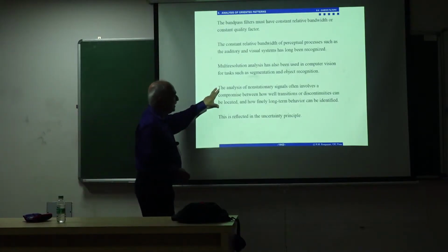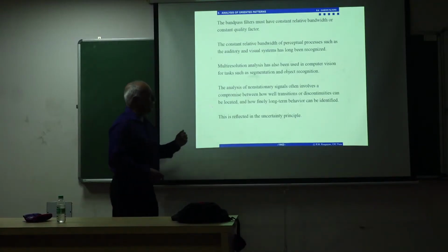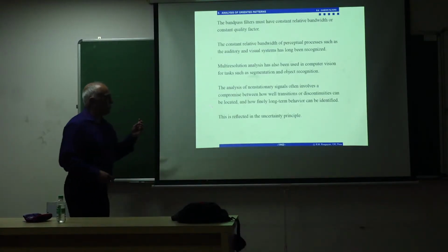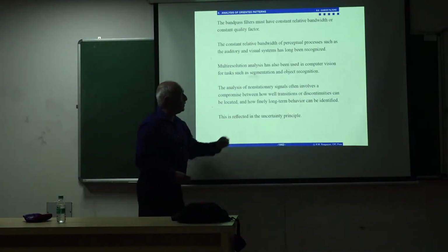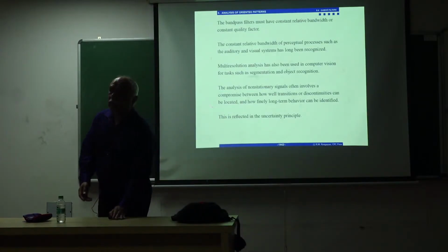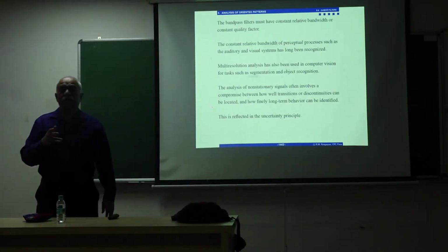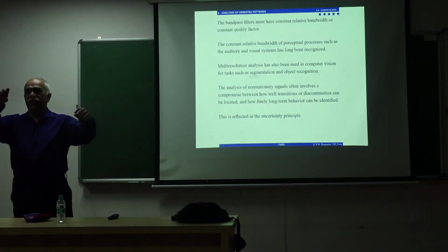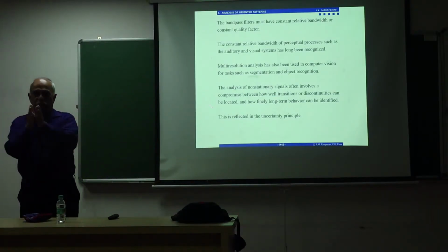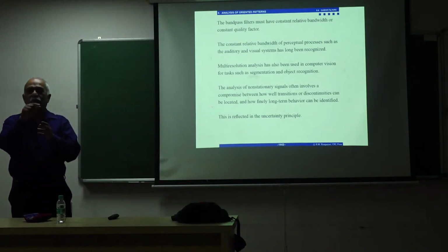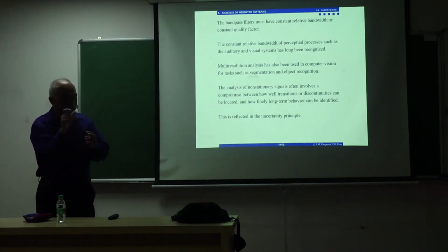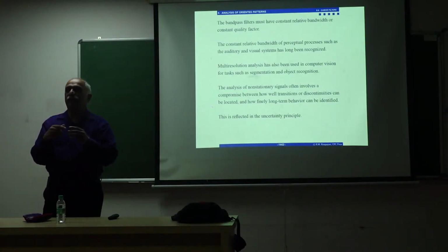In the case of non-stationary signals, you need to compromise between how well transitions or discontinuities can be located and how finely long-term behavior can be identified. In the case of speech signals, I mentioned there are plosives that are transients. So if you use a big window, the transient will be lost in that big window. So you want a small window. But if you use a very small window, you'll be looking at maybe one of the wavelets of the repetitive function in the case of voiced speech.